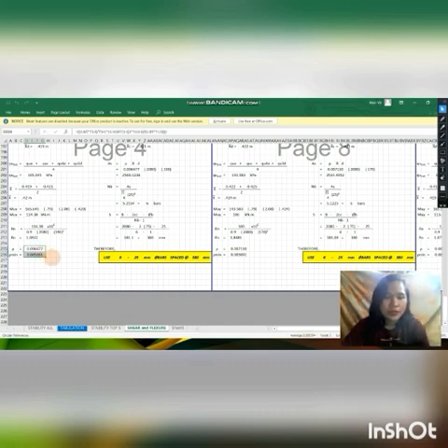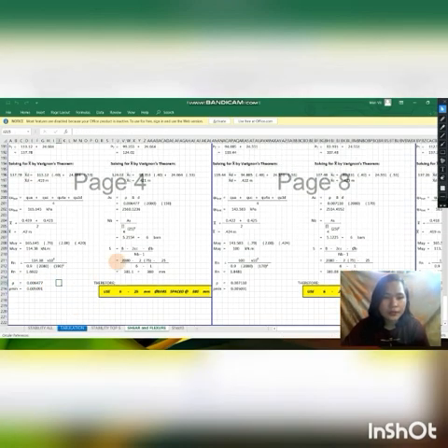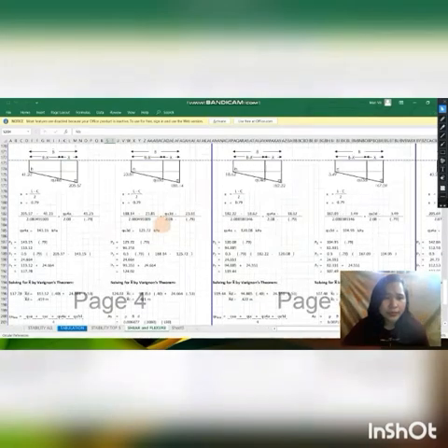Comparing these two values, the larger value is the rho, so we will use the rho value of 0.006477. Substituting that rho value in our formula for our area, we will arrive at the answer of 2,560.1236 millimeters squared.